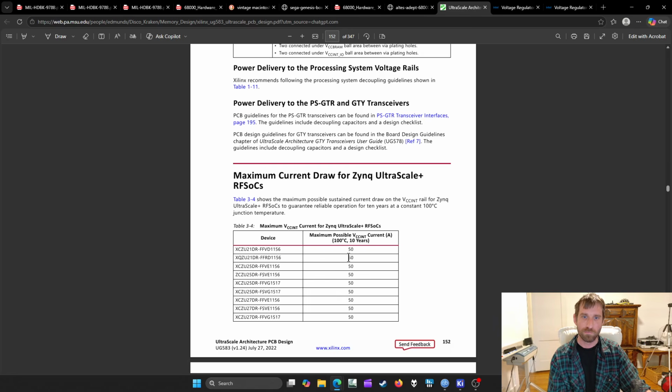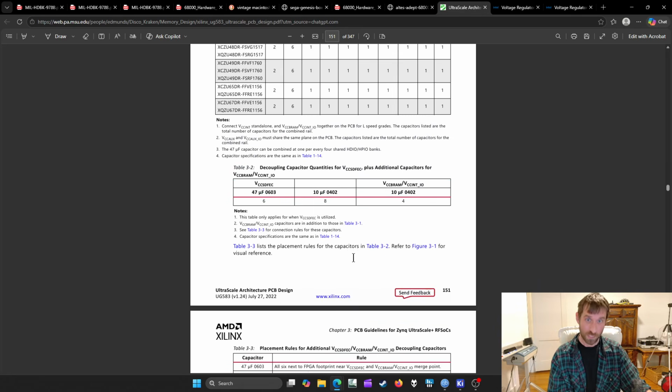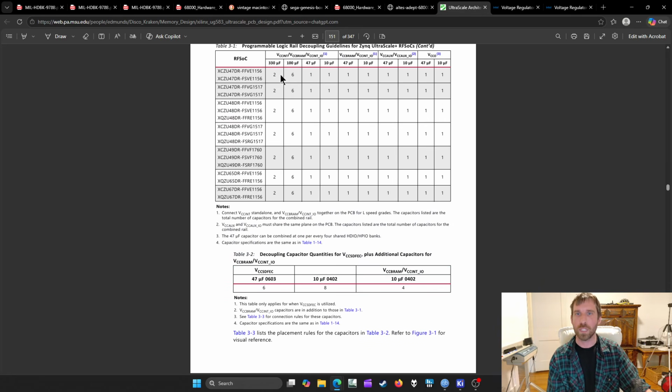So we've been doing some power here. So this will tell you what to do for capacitors. These are big boys here. So there's something like 14 caps down here, and then you got to also do this sheet. So another 18 here. So you're going to have 30 plus capacitors that are at least 10 microfarads, some much bigger. So yeah, just read your data sheets and do what they say. That's all you got to do.